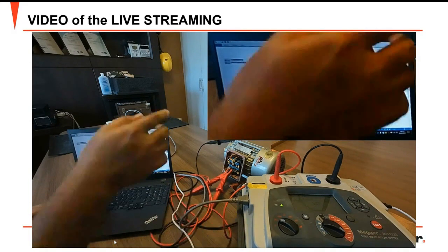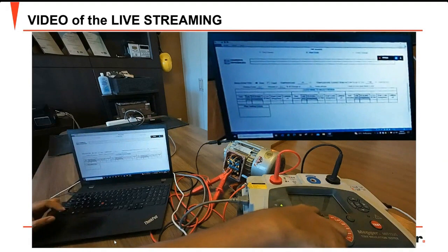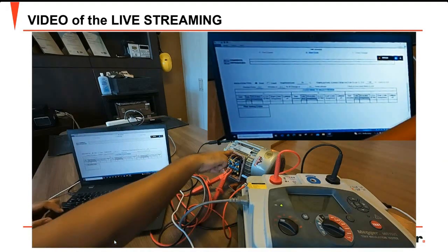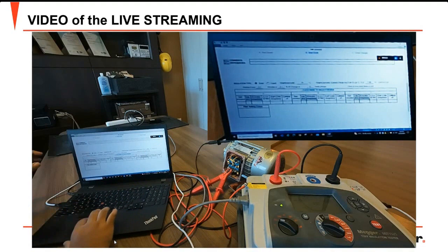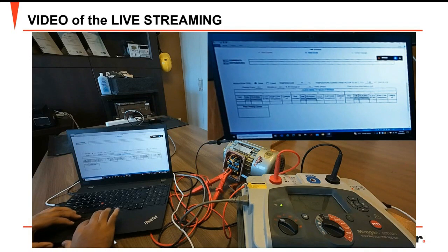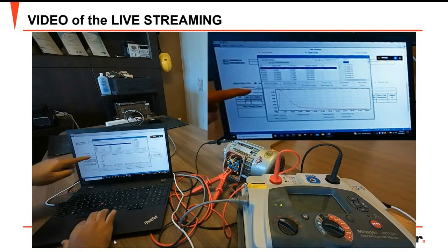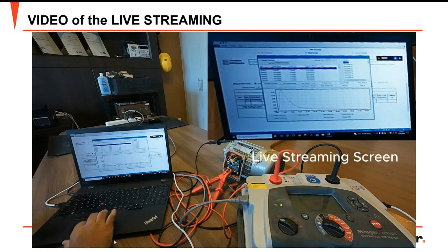Okay. So as you can see here, we have selected 500 volts connected to the motor here. Then you can click anywhere onto this voltage or this one reading, megaohm. Just left click, and then it will open this box here.